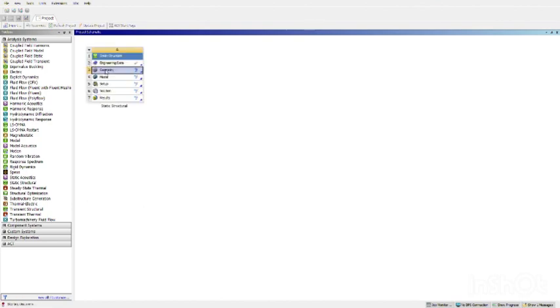So we will double click it, and actually we want to draw our shape in SpaceClaim. So we can right click it. Now we will right click on the geometry, and we will click on New SpaceClaim Geometry.